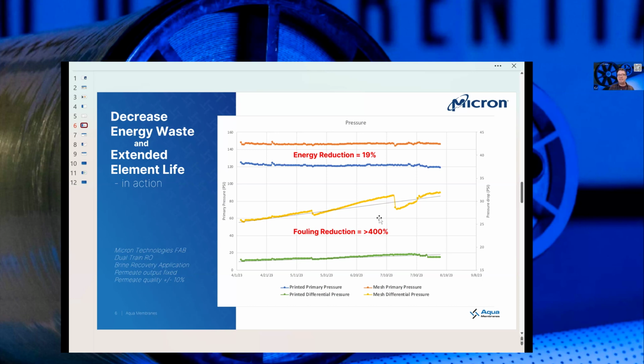That gives us a little bit of insight as to what was occurring, what was the cause of the pressure drop increase. Because most of the time, if a system is scaling, the pressure drop increase occurs in the second stage where the concentrations are higher. Since this was occurring in the first stage, that's more consistent with a biofouling event. So not a conclusive point there on the origin of the mechanism, but some indication that this specific site was seeing some differences in terms of biological fouling.